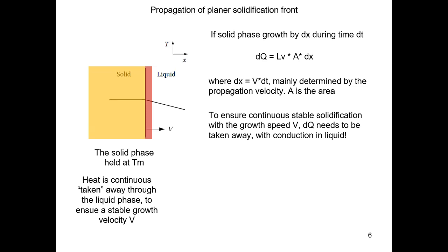So even if you didn't take this class, when we talk about diffusion, we mentioned this at the end of our lecture. Mathematically, the conduction of heat is very similar to the transport of atoms through diffusion. We have virtually the same type of laws. The reason is that all of these conduction or transport processes are a first order approximation. So you're always going to have the flux proportional to the driving force, and the driving force is the gradient of some potential field. The reason is we're looking at linear first order dynamics. So we see a lot of mathematical similarity between these things.